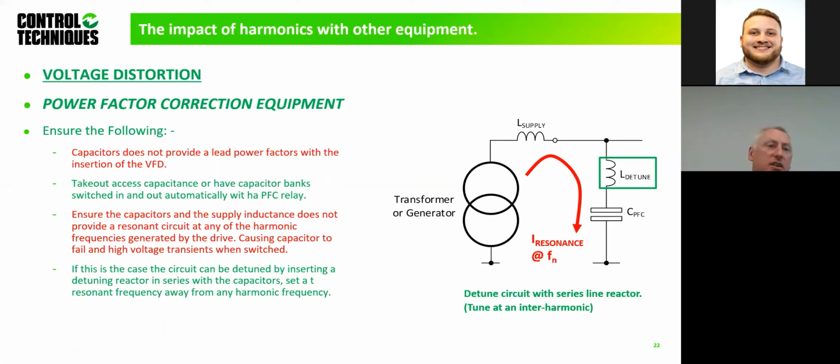Again, you can challenge yourself. You can do it, but your power factor correction capacitor people or your filter people will be able to help you analyze what reactor needs to go in there. And usually they set up a tuning frequency to an interharmonic type value. For the fifth harmonic, 300 hertz, they might decide to tune it at 275 hertz or something like that, which is never going to get there, or even a higher frequency. So it tunes it away, keeps the capacitor doing its job with the 60 hertz component.